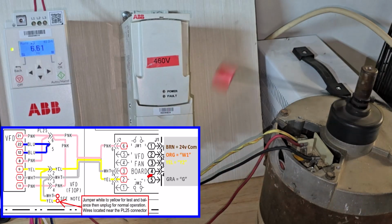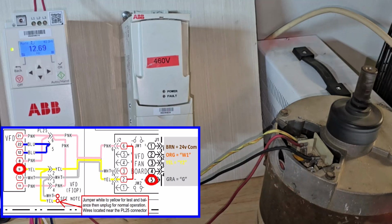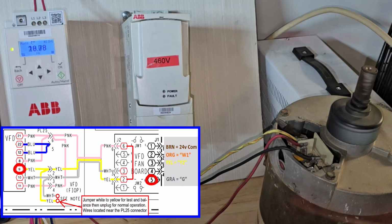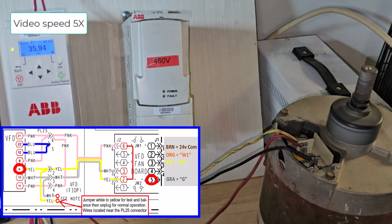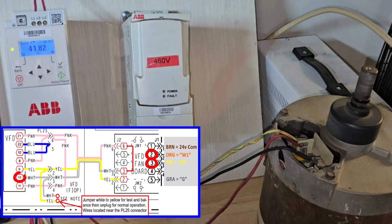Energizing thermostat G should operate the drive at 40 Hz. Note the 30-second acceleration ramp time. Now with a second stage cool or a heat thermostat signal, the drive should switch to 60 Hz.